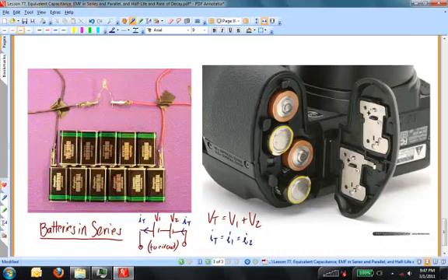You would get a nasty shock from this array of 9-volt cells on the left, were you to grab both terminals with your hands. It might not kill you, but it just might. There's 1, 2, 3, 4, 5, 6, 7, 8, 9, 10, 11 9-volt cells connected in series. 9 times 11 is equal to 99, almost 100 volts, and you would get quite a jolt out of that.